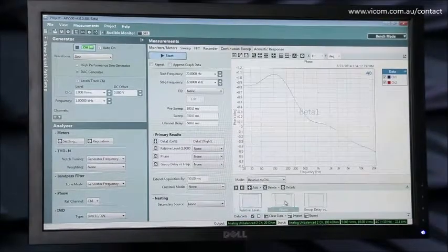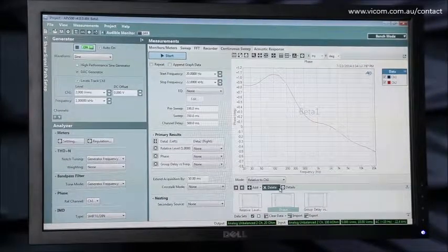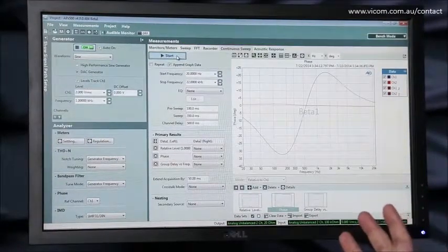And at the same time, I've measured phase. Now this is the phase between the two channels, and again you can see it's pretty flat. It's only plus or minus a degree or so. And again, I'm sure that's just because of the settings of those EQs and so on. But if I radically change the EQ, let me move one of these around a little bit, and let me do an append and do that again, and you can see, well, now the phase difference between the channels looks completely different, and that's because I've skewed the EQ on one of the channels relative to the other.